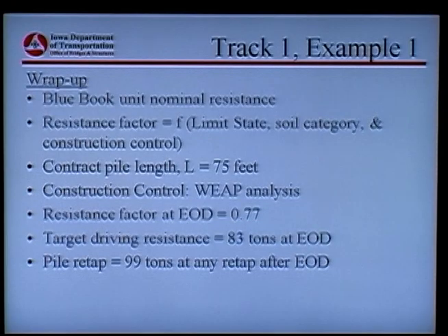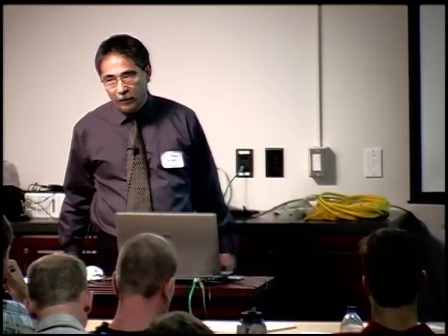The other comment I could make is that part of this investigation study was looking at a lot of different methods of analysis. We didn't just default to the Blue Book. We looked at a lot of different ones. The reason the Blue Book won out is because the department in its wisdom has been keeping tabs on pile load tests for a long time. The Blue Book was based on its own version of calibrating against those load test results. We're using the same raw data. We have more data now than we did when it was first developed back in the 60s and 70s, right? But still, there's enough history that it's still trending the same. So it's still valid to this day.